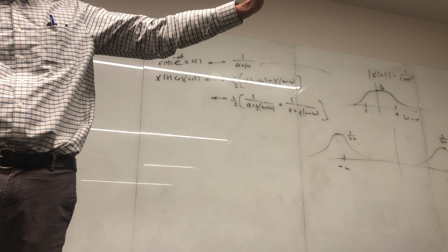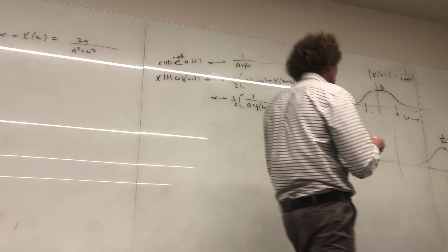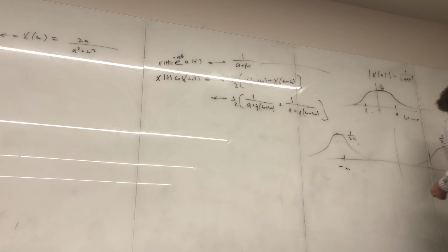100 or more kilohertz, so that the actual bandwidth here, if you think about the bandwidth on these things, this is half power, this is the peak power, this is the half power bandwidth. This bandwidth right here is fractions of the actual carrier frequency. It's very, very small. So you can transmit it on an antenna that's tuned just for the carrier frequency. This little bit of change doesn't change the impedance of the antenna much, and you can transmit it.